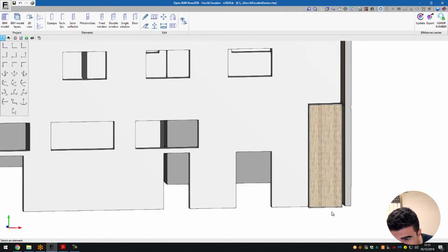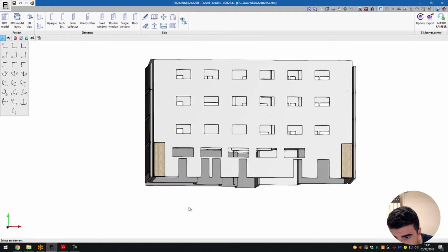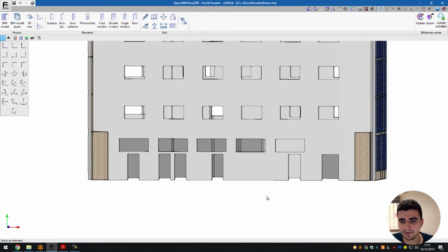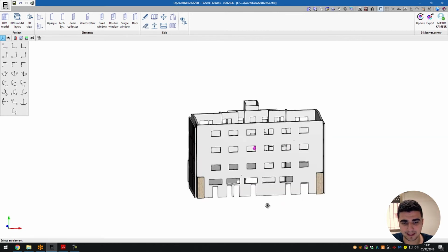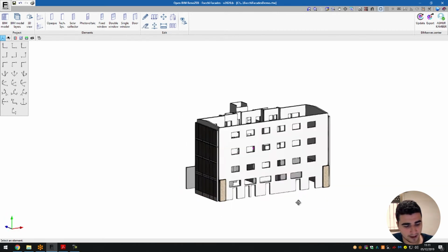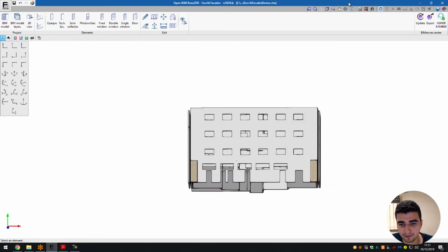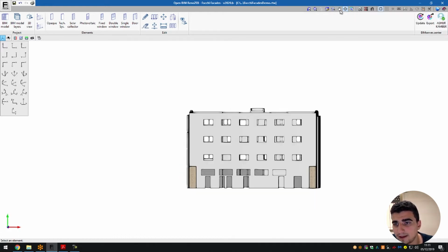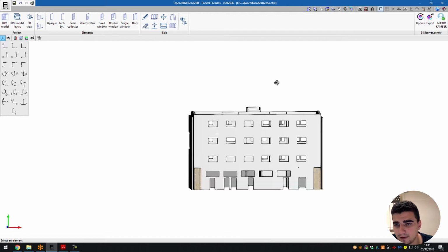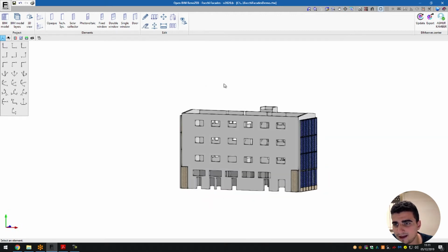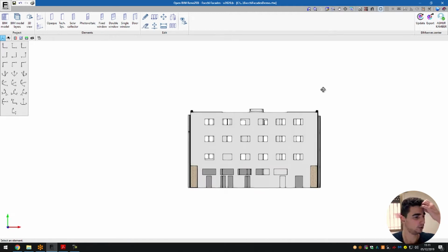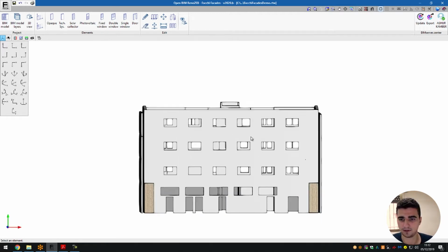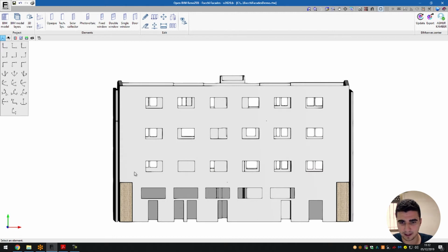So that's done. Now, as you can see, I'm zooming in and out and also holding the control key to pan around the building. You can also do that by clicking this button here, the 3D orbit, but again, you have to unclick it. The control key is such a great shortcut to be using when configuring our facades. Anyway, we can now configure my facades along the side of the building as well.